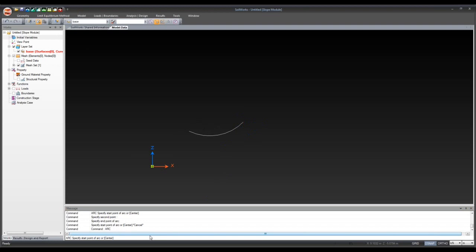So now I just typed in arc in the command bar. It'll ask for the center once more, and I can type in a second point if I want something set. So let's say it's 20, 20. So as you can see, now it's something a little more set. But that's how you use the arc command option. And this is particularly useful when you're doing certain types of slopes. What you can do is connect from end to end, and you can draw your arc that way.